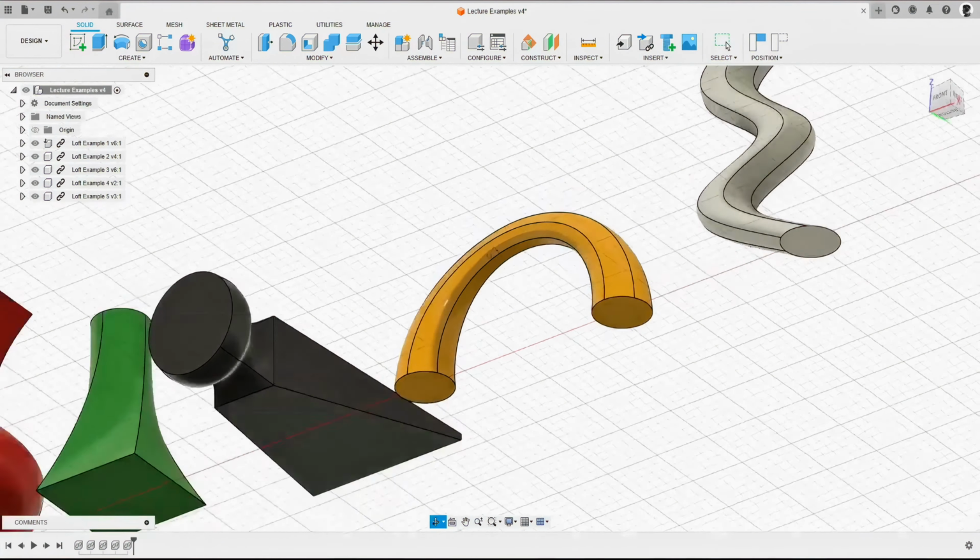And now let's create a new sketch. Hit C on the keyboard. And now we're going to sketch on this plane here. Okay, so we're sketching here. We've got our origin there. So let's start from there. Bring out a circle. And let's go for 200 mil. Press enter. Okay, got about 2 sketches in there. Let's finish the sketch. Hit C on the keyboard. Let's go for the 3rd plane this time. And I'm going to start just at the origin there. I'm going to drag that out. Let's go at 18 mil. Let's enter. Okay, got our 3 sketches. Finish that sketch.